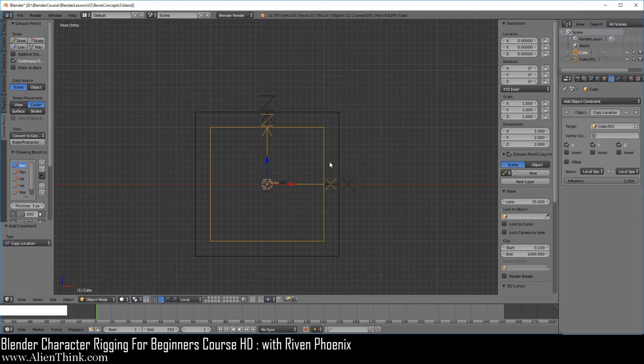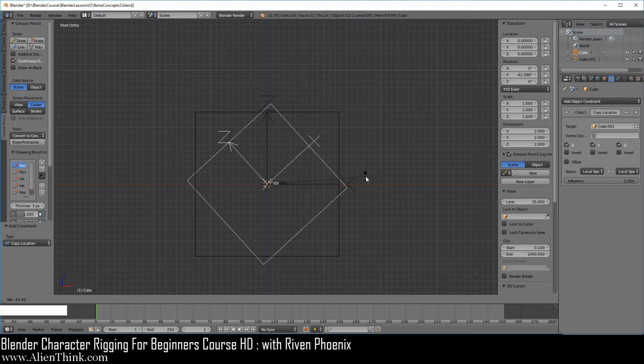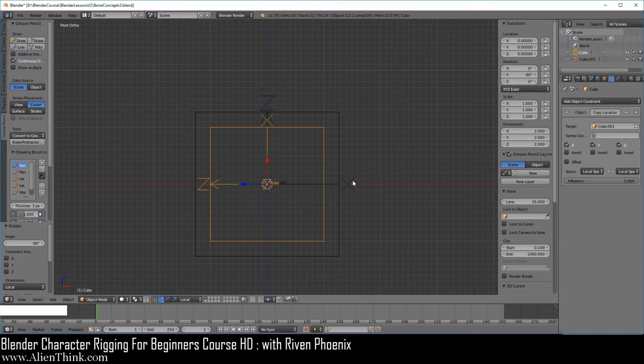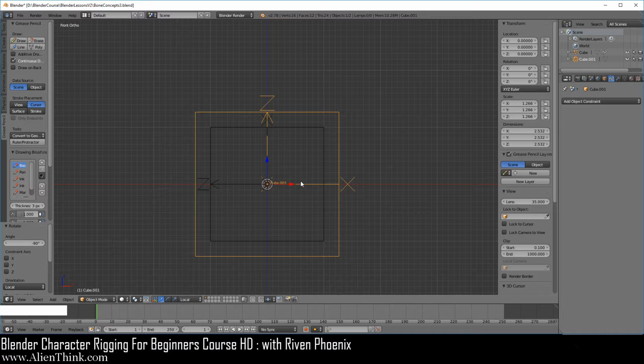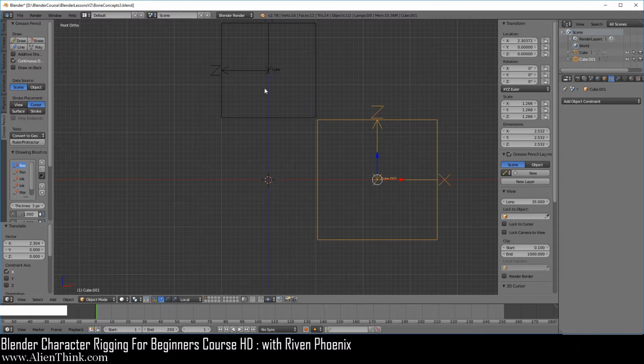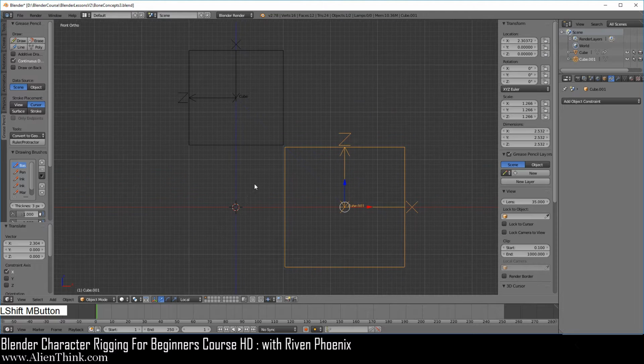Both of them, right? Because if you click on this object and press the R key to rotate, now press the Control key down, point the X up over here. Notice that if you click on this object to move along its X, this object will move along its X in this direction. So you could say, well, that's kind of pointless, right? Why don't we just create parent-child relationships and just rotate the parent? Because then we can point to this object in any direction we want.